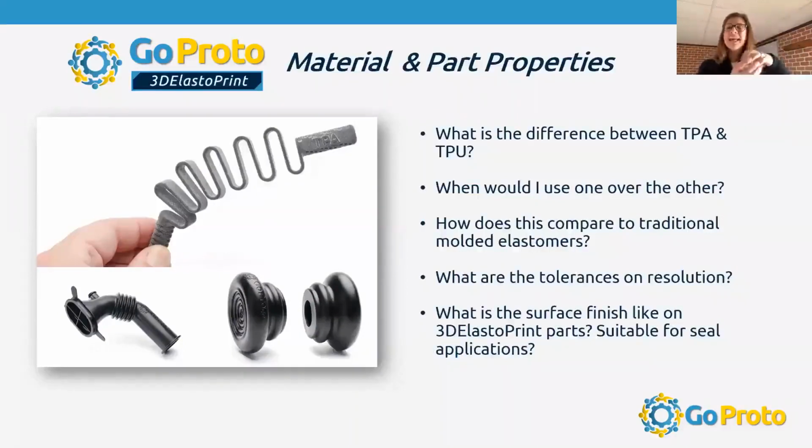You can bend your part. And it worked. It was equipment for spraying paint. And as a prototype, it absolutely works. So for sure, it would be good to look at for sealing for prototyping, because I understand that can be an expensive process. I just don't know that 3D printing it could then be used in production. But for sure, I think it should be looked at for prototyping seals and prototyping new equipment and design. Also, once smooth, if you drip water on it, it will bead right off. And water and other liquids as well.